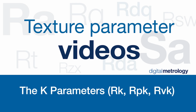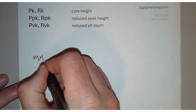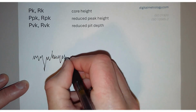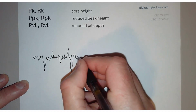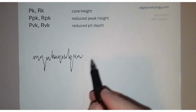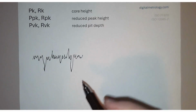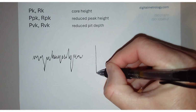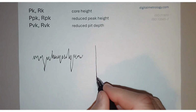Most surface texture parameters treat the profile or the surface in 3D as if it were one particular signal. Now, in many cases, that's not true. For example, this surface has a smooth zone in the middle with some peaks out of it and some valleys sticking out of it as well. And this is where the RK parameter family becomes useful.